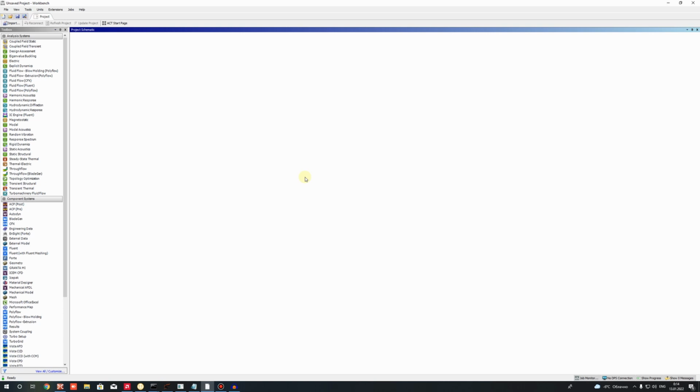Welcome to this video where I will show you how to perform simulation of a 3D model of a centrifugal pump impeller, which we designed in the previous video tutorial in part 1. Today we will continue this video tutorial and we'll create the mesh and set up the boundary conditions, make the simulation, and try to predict the head and hydraulic efficiency of the impeller. Also we will find the power on the shaft.